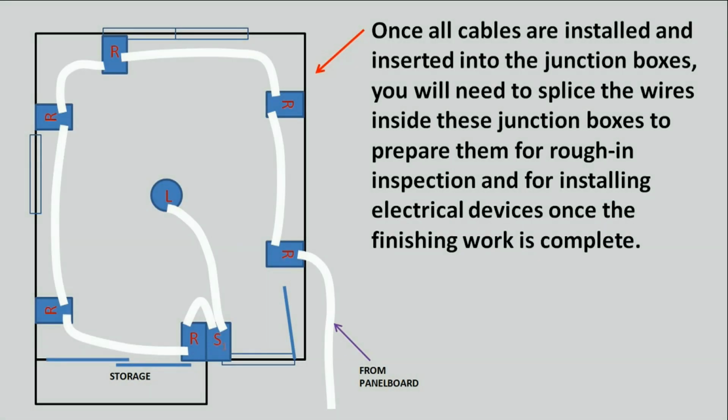Once all cables are installed and inserted into the junction boxes, you will need to splice the wires inside these junction boxes to prepare them for rough-in inspection and for installing electrical devices once the finishing work is complete.